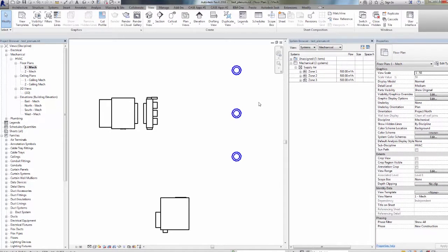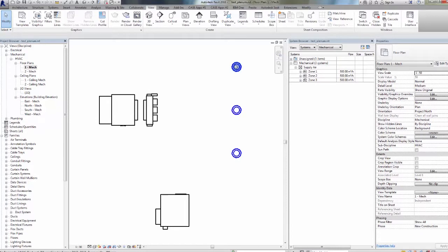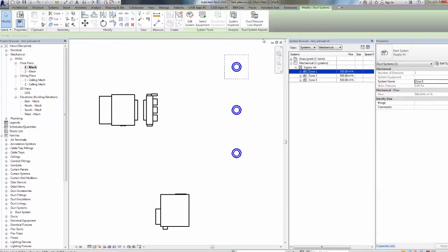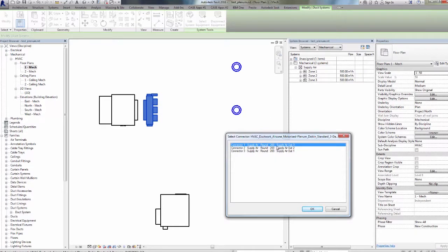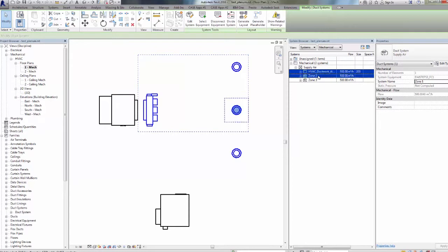Now we are assigning the plenum to all these systems as equipment by means of the output connectors. We see how all these systems are below the plenum. Now we are creating a system composed by the plenum and the indoor unit. From the plenum we create an air supply system and call it fan coil plenum. The plenum still has two free connectors.